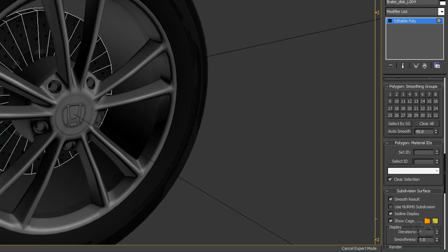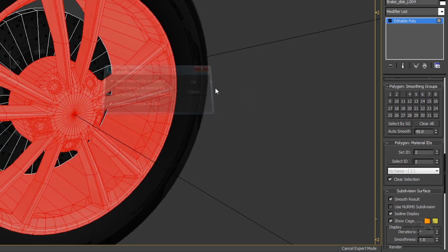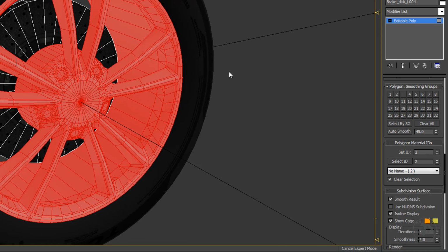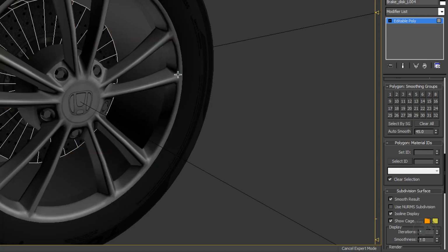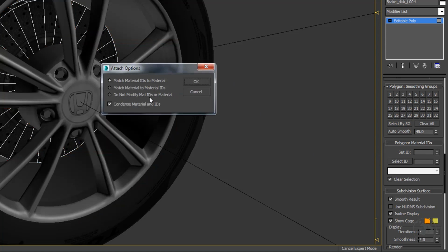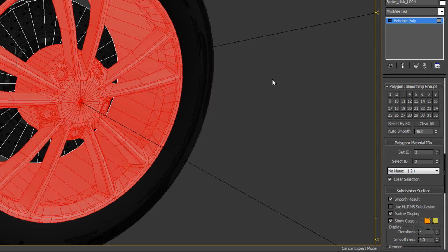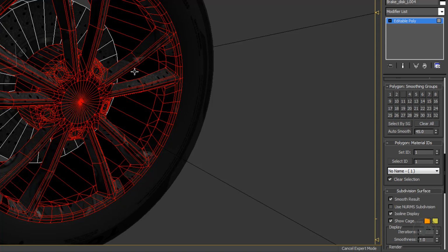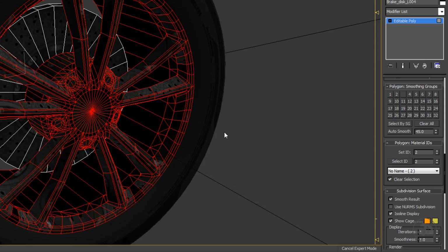The attaching process will keep following the same attaching sequence, and it will assign new IDs to the attached objects based upon their attaching sequence. If you try to change the Material ID of any polygons or faces within multiple material IDs assigned to that object, the polygons will render the material of the new ID.